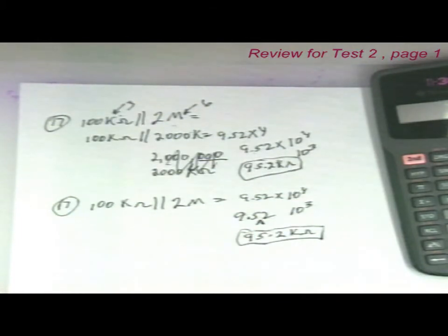Okay, let's do this one again. If one resistor shorts in a parallel circuit, what's going to happen to the total current? It's going to increase. It's going to increase a lot. It's going to increase so much that you either blow a fuse, or if you don't have a fuse, you're going to blow a component.